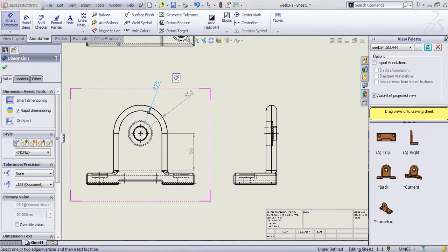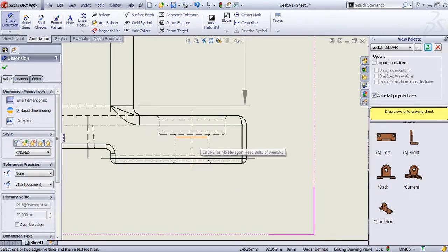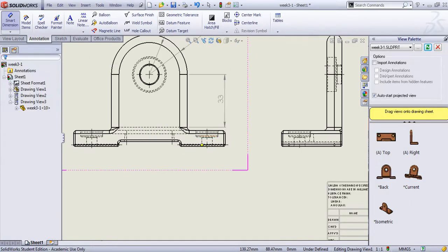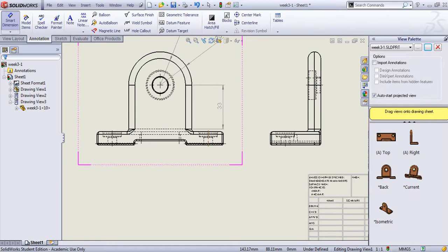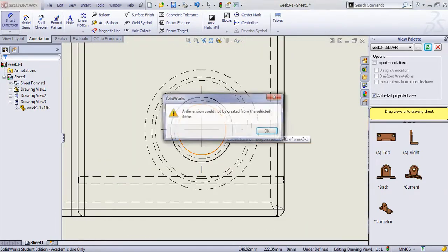This one. Now there are certain rules applied for selecting dimensions. You always refer to the solid line, not the hidden line. So I won't choose this one as a dimension, although if I did, this would be the diameter of the bottom counterbore, but I won't do that. And for dimension, if I want to do this, why not go here and then pick this.